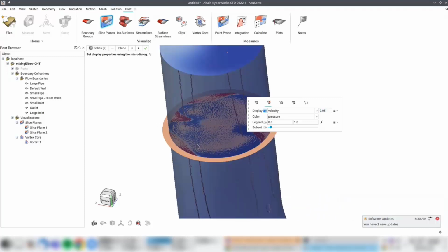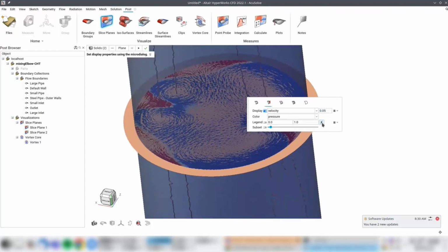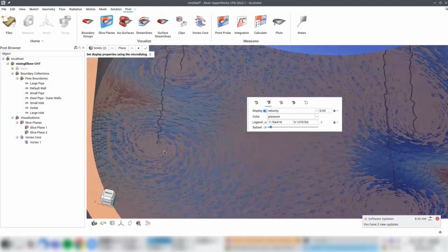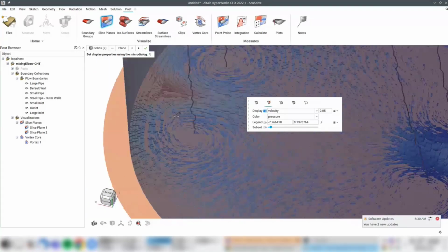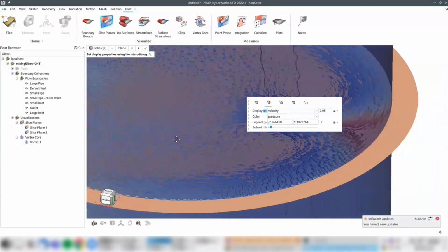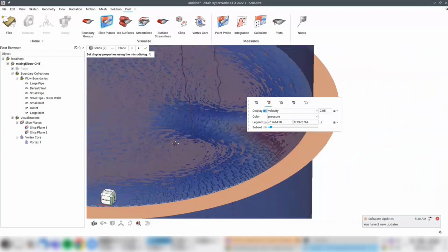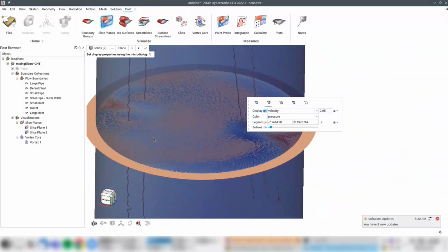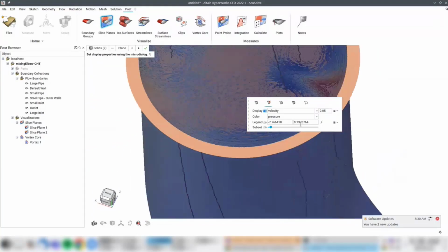And we'll zoom in. And let me change my local legend here. Yeah, so now if we zoom in, we can actually see that our vortex cores pass through the center of where we see these rotational vortex structures in the velocity field. So it's just a little bit of a check of how well the vortex core algorithm is doing at actually identifying the vortex structures. And it looks like it's doing a pretty good job.